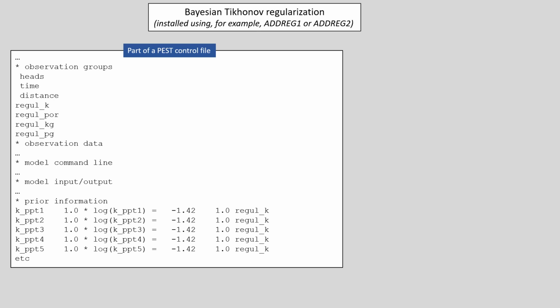When we do this for parameters like pilot points, it's much better to use a covariance matrix than weights. This assures that any emergent heterogeneity is spread out and not just concentrated at pilot points, producing a bullseye effect.